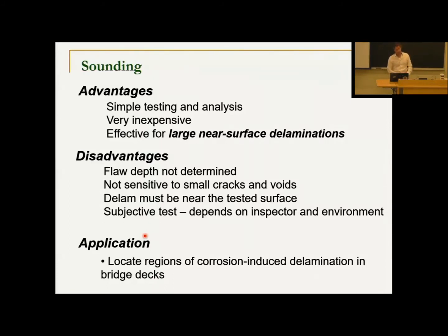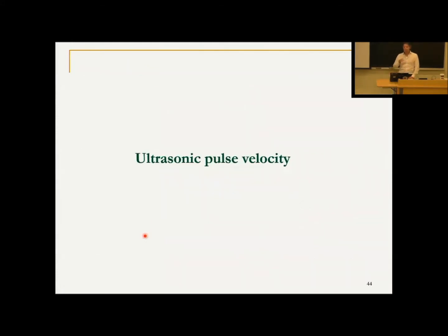Right? But it is not exceedingly fast. Remember, we have to have an inspector tapping and listening, so we're going at slow walking speed. So this is not an exceptionally fast method. Okay. Next order up in complexity is ultrasonic pulse velocity. So this is a simplified, specific test of ultrasound that works for concrete.